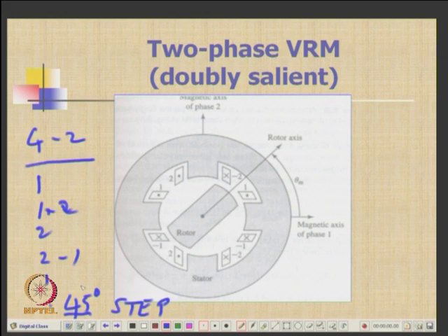So, there is another configuration. Earlier there was only a coil which was housed in slots, here it will be wound on poles. So, you have these 2 coils here and these 2 coils here must be in series, okay. As good as you pass a current I1 through this and then it can come here, okay, then come out here.